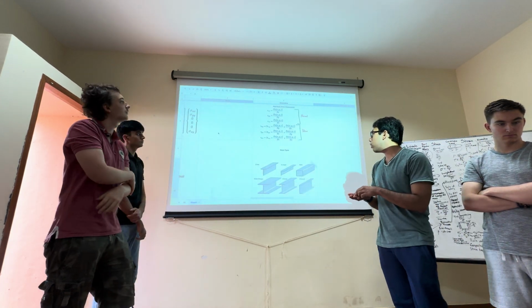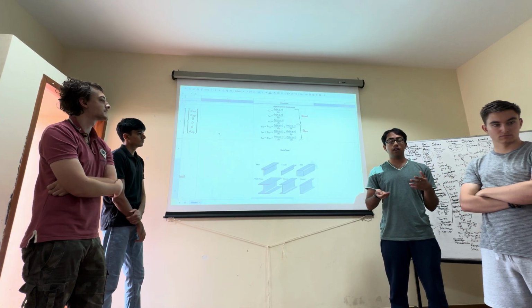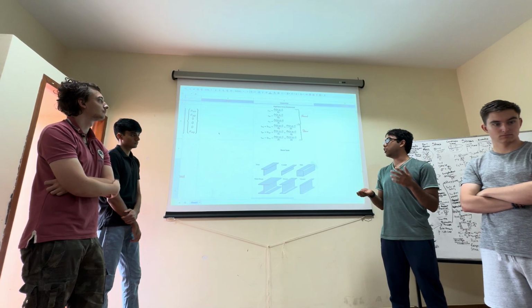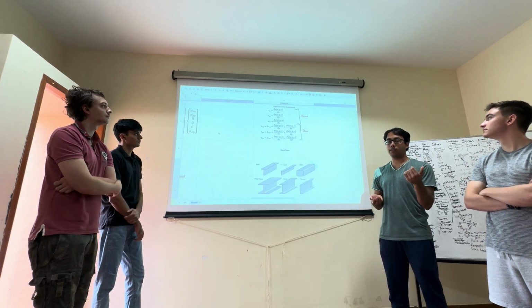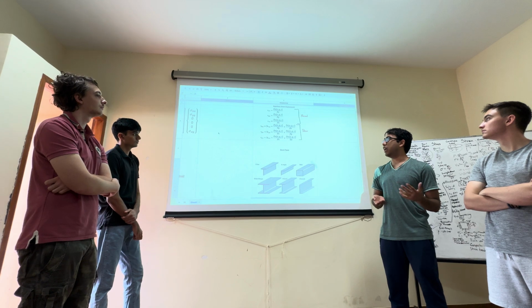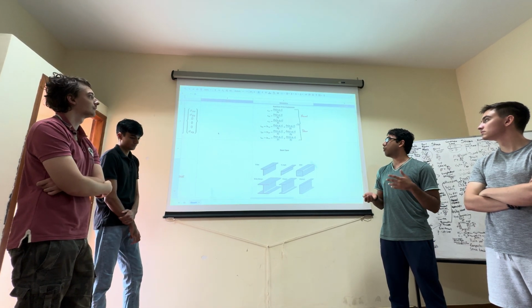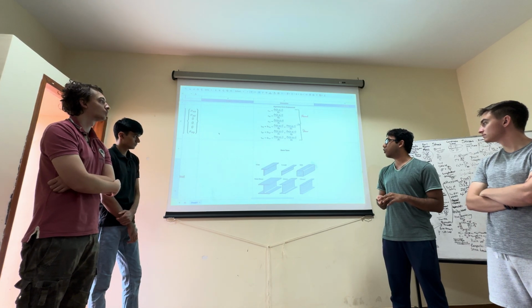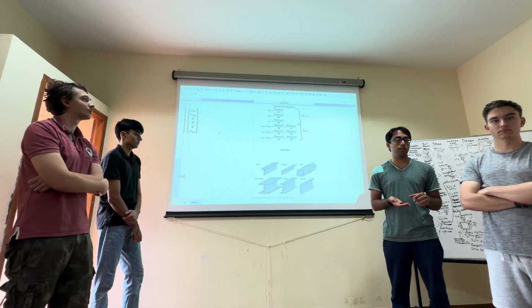So also what we have is this kinematic equation that basically relates strain to displacement as a form of deformation. In this case, we're specifically talking about rigid body structures. That's why you'll see that the derivative of u, the displacement field, over dx will give us a strain in the x direction. And this is the same for the other examples of normal strain displacement, whereas in the shear direction, we're adding two different derivatives in order to finally figure out what the strain is.